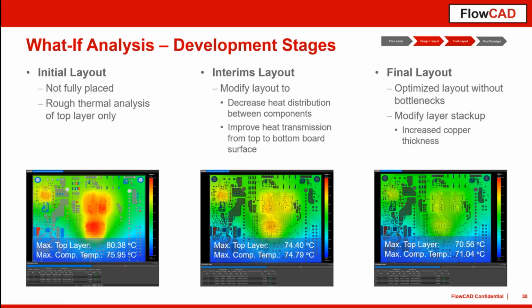And that is something that may really help you to do such what-if analysis very early in the design, to get a feeling about your components if they get overheated. Or you can say, okay, maybe it's even better to spend a little bit more money for our PCBs by using thicker copper layers. But in this case, we can leave out the necessity of additional heatsinks for our devices. And that is something that I think is very, very helpful here, especially in the pre-design phase, to define the final layer stack-up and also to see how that works in the complete design environment.